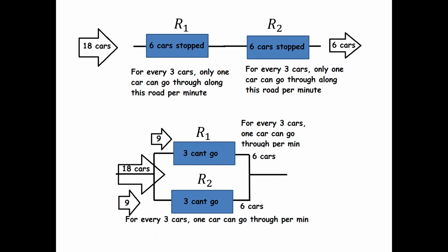Because you have resistors in series, the resistance is added, it's cumulative. However, if you have resistors in parallel, because the current is split before it goes through the resistor, a lot more current can pass through.